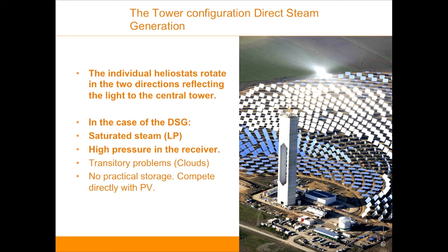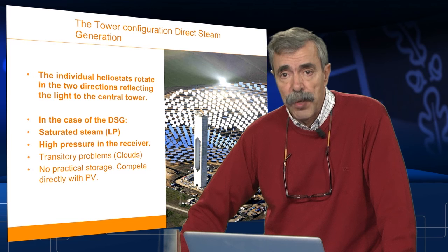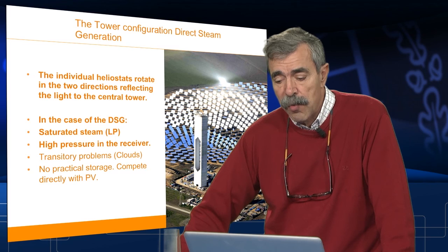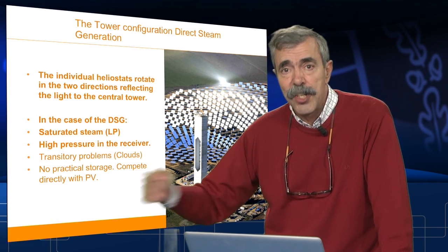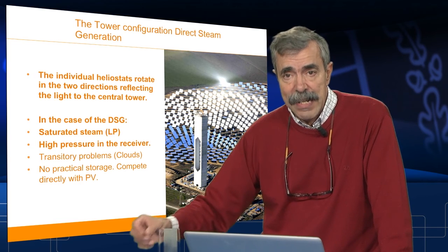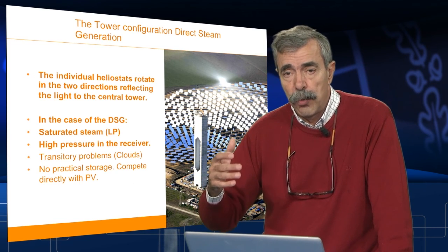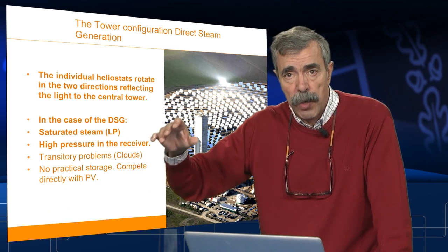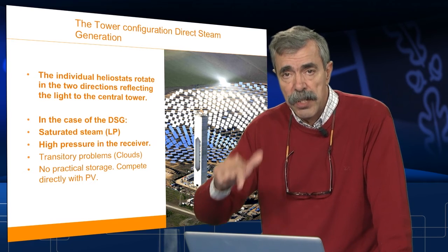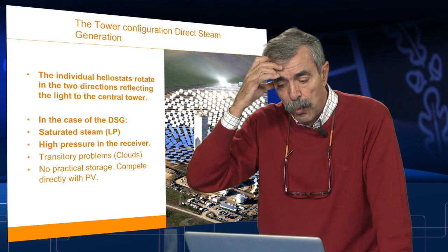This is absolutely necessary to be able to stop the turbine in a normal procedure, and not destroy the turbine the first time you have to stop the receiver, because turbines do not want the conditions to change fast. A steam turbine needs a gradual decrease of temperature and pressure. Otherwise, you are damaging the internal parts of the turbine.